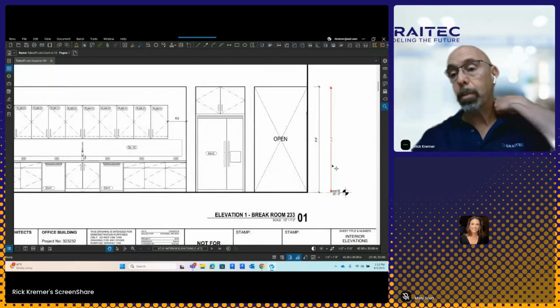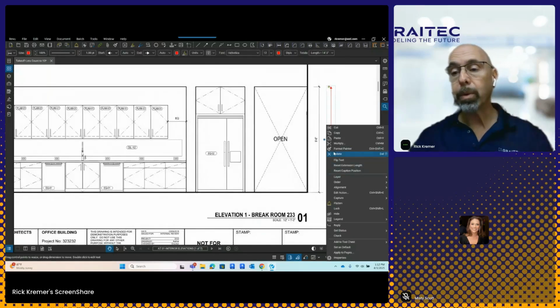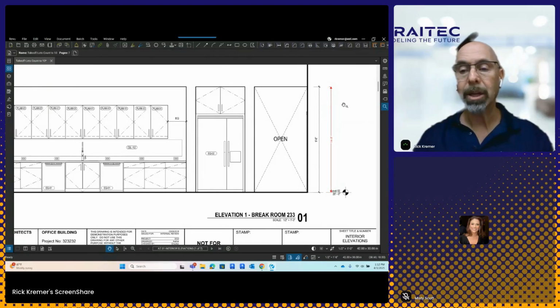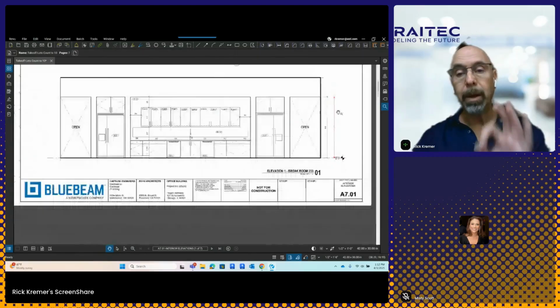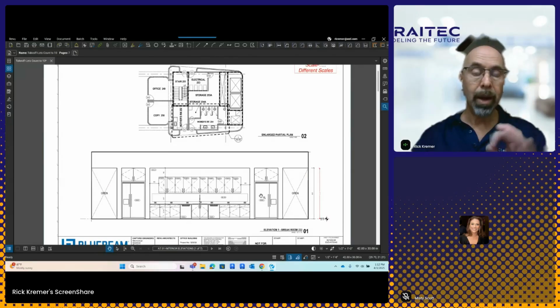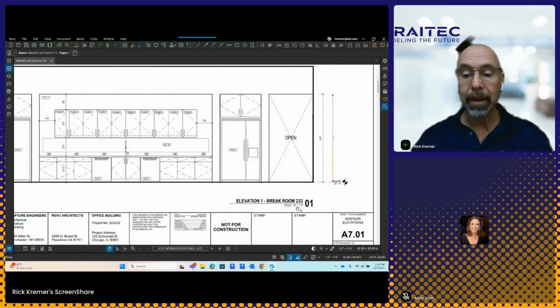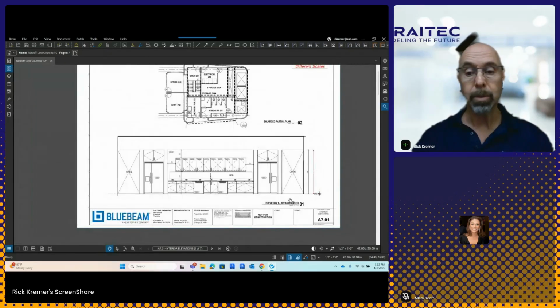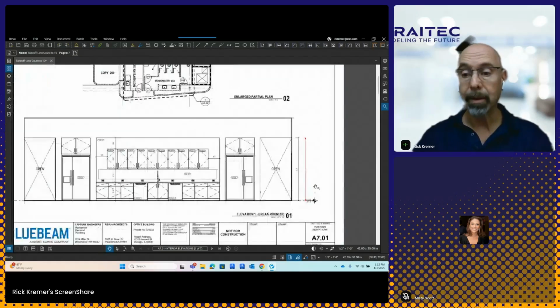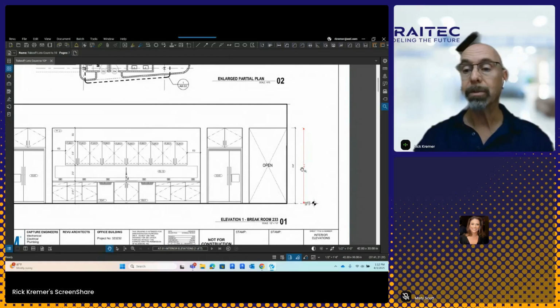So what do we do? Basically, we're going to go through. I'm going to leave this because you're going to see how this dynamically changes. We're going to calibrate the drawing according to a custom measurement. And matter of fact, anytime that I go through and scale drawings, I got to tell you, I never trust that the drawing was printed to scale. And this is a case in point. This was perfectly printed, but zoomed to fit or something. It's not true 1/2 inch equals a foot.